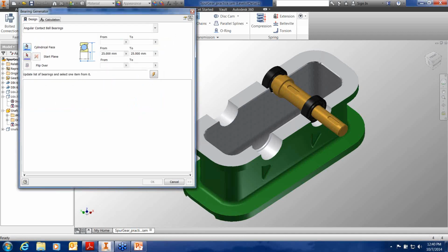All right, now at this point we have to start giving the design accelerator a little bit to work with. I could type in values up here, or make choices from values, for my outside diameter. It's maybe a little hard to see on your screen, but I've got a little icon here: the top section has to do with the outside, the middle section is the inside diameter of the bearing, and this is the width of the bearing, so it corresponds with our icon here.